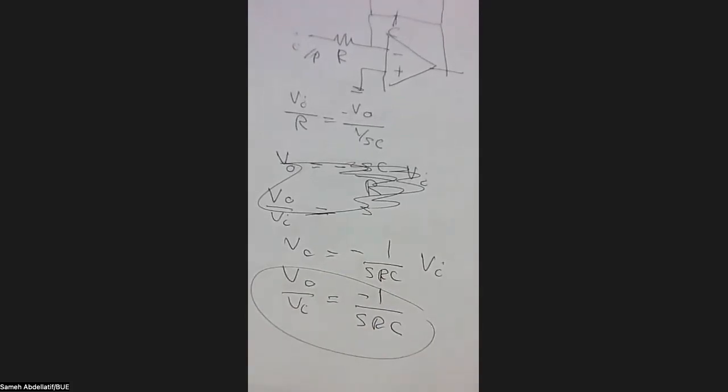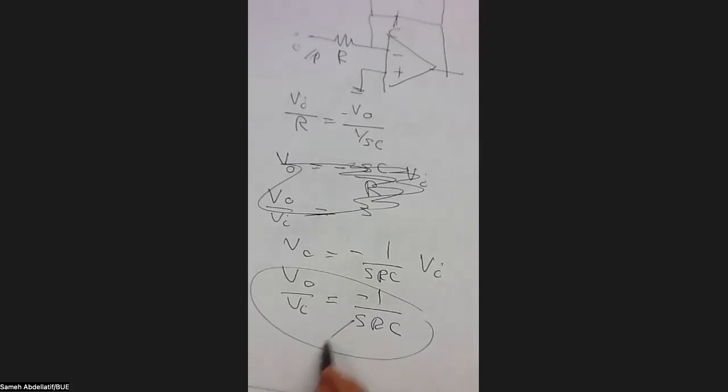To explore the difference is very easy. Let's express what we can call the DC gain. Here, the DC gain theoretically is equal to infinity. It's very high because a DC gain means that omega equals 0, which means that S equals 0, because typically S is J omega. So if you put S here equal to 0, that means this term is equal to infinity.